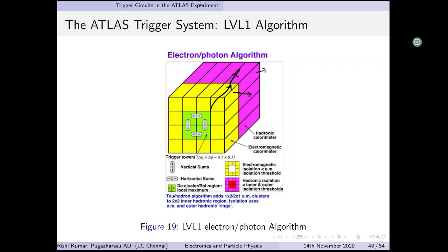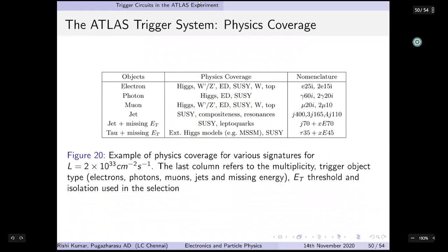But even in here, before I even go to these combinatorial circuits, instead of integrating them, I do vertical sums because of the discrete nature of these bits, and then I compare them with the horizontal sums and then obtain an average, and then I can talk to my trigger, and then my trigger can talk to my DAQ. And this happens once for the electromagnetic realm and then for the hadronic realm. This is just a repetition of what I said earlier.